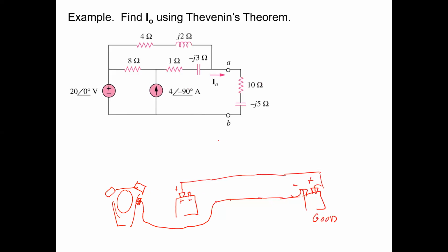And batteries do explode, especially when they're drained, like if you left your car lights on all night. As batteries drain, they release hydrogen, and that can build up in the engine compartment. Hydrogen is lighter than air, so it should go up as soon as you open the hood, but I have heard stories where people blow up batteries, and then you get a bunch of acid everywhere.